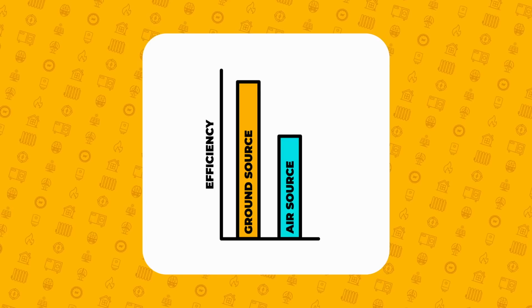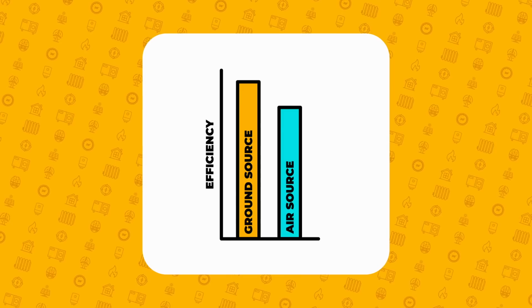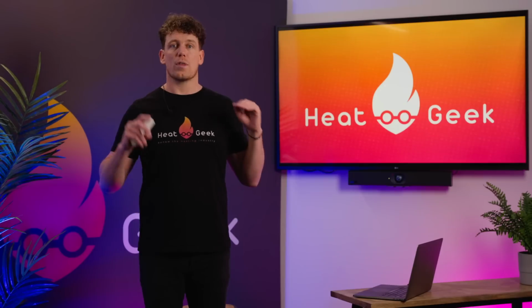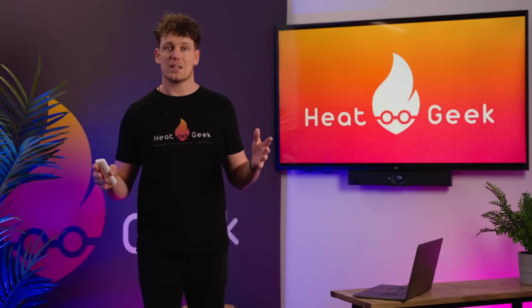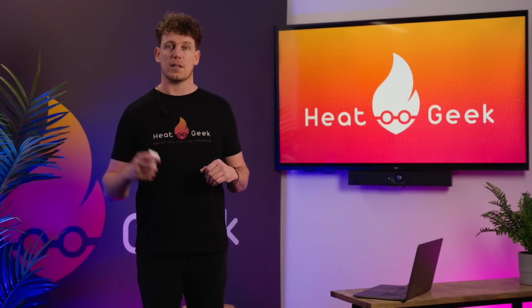However, recent improvements in heat pumps have really narrowed the gap and put air and ground on a much more level playing field, particularly with lower flow temperature systems. The heat source temperature is much less important than it used to be, with a higher importance placed on the flow temperature required for the radiators. In other words, hydronic design, such as what's taught in the Awakening and Mastery courses from HeatGeek.